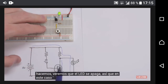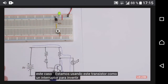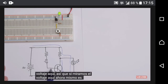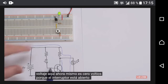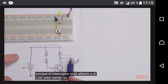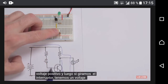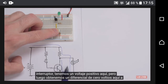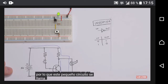So in this case, we're using this transistor as a switch to invert the voltage here. If we look at the voltage here, right now it's 0 volts because this switch is open, and the LED is seeing a positive voltage. Then if we turn the switch on, we have a positive voltage here, but then we get 0 volts differential across the LED, and the LED turns off. And so this little circuit is called an inverter.